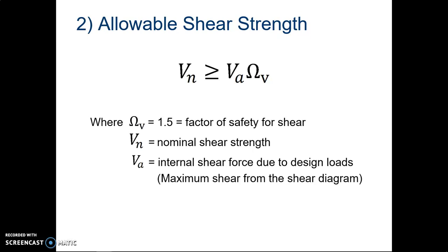The beam bending so much and then it becomes unstable? Or the beam not bending so much, but just so much loading on top of it that it just snaps in half? Think about it for a second. Is it going to fail first from bending too much and then becoming unstable, or too much load that the metal just snaps in half? If you guessed that it'll fail first from bending too much, you're correct.